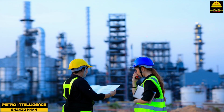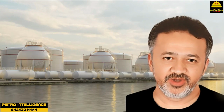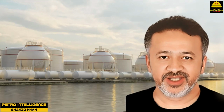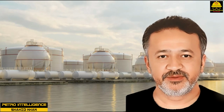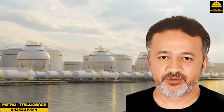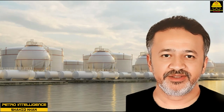Inspection. Prolonged and safe operation depends upon good inspection practices for assurance that equipment is being maintained in a safe condition and that off-stream time is reduced to a minimum by anticipation of necessary repairs. In general, the scope of work includes all pressure vessels, heat exchangers, storage tanks, process piping, pumps, relief valves, furnace tubes, fittings, breechings, stacks, and tube supports. Any equipment subjected to pressure or temperature extremes must be inspected periodically.